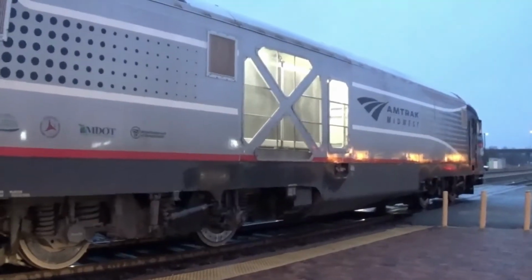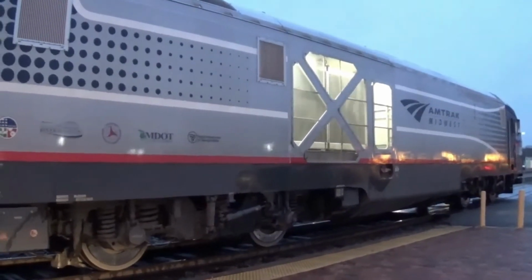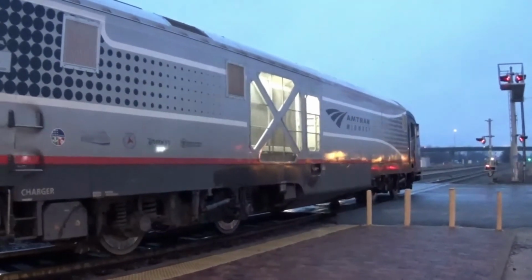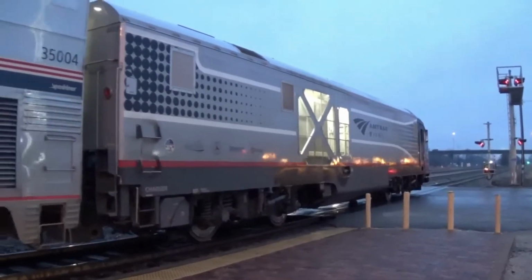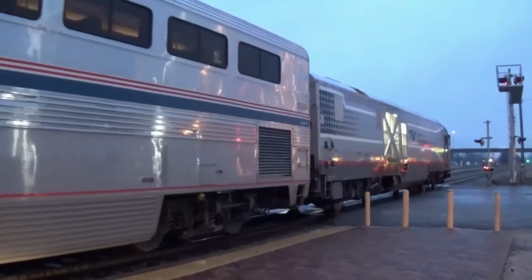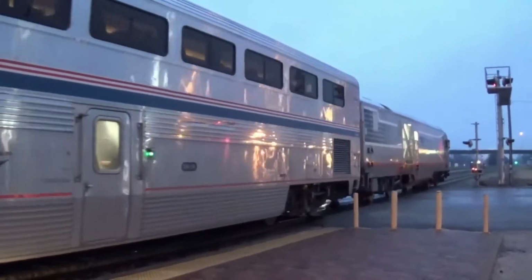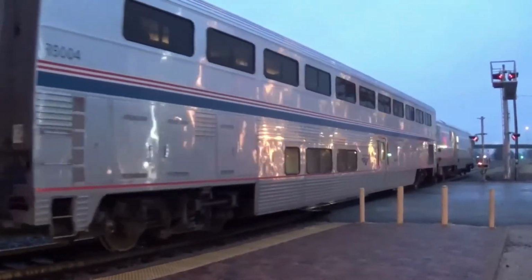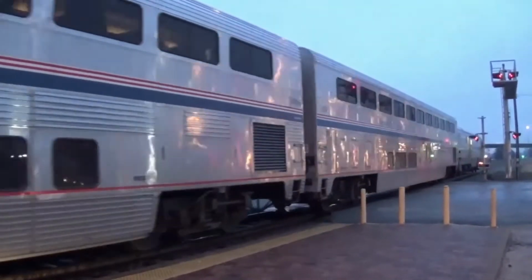Starting tractive effort is the tractive force that can be generated at a standstill. The figure is important on railways because it determines the maximum train weight that a locomotive can set into motion. Maximum tractive effort is defined as the highest tractive force that can be generated under any condition that is not injurious to the vehicle or machine.